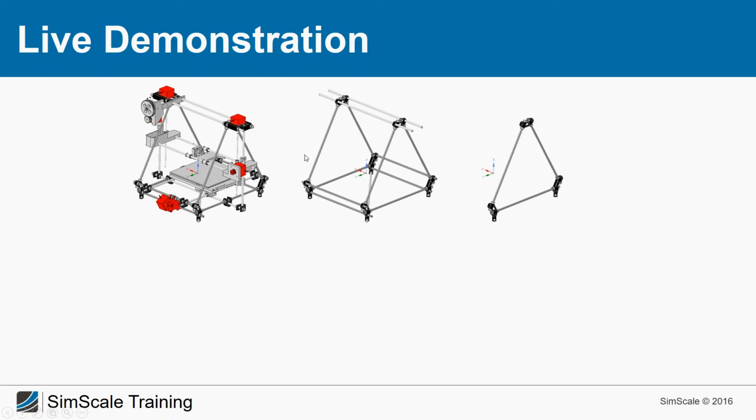Just imagine, if this frame starts to vibrate, everything is moving, so also the head of the printer, the extruder, and when the extruder is vibrating, this will make it very difficult for you to control the position and therefore to ensure the right setup of the different layers when your part is printed.